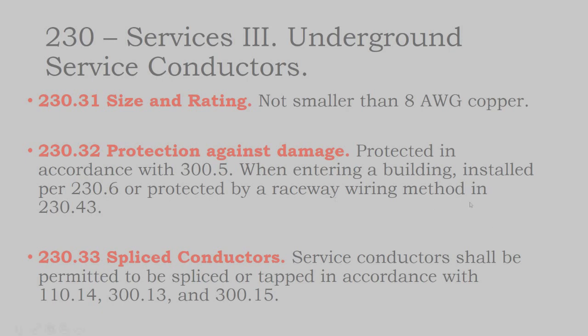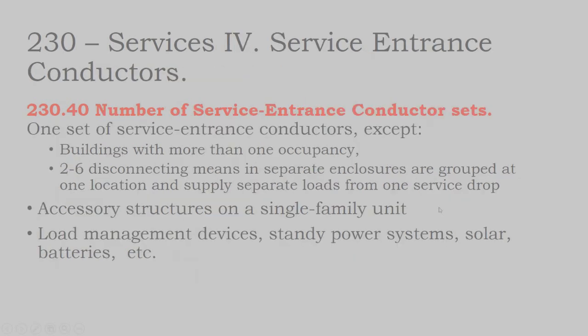Service conductors are permitted to be spliced and tapped, but only under certain conditions. So if you're inside an electrical box for a supply side tap, you are allowed to tap onto your service conductors. And how many service conductor sets can you have going into a building?